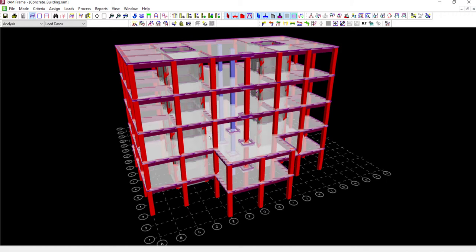Basically all the degrees of freedom are consolidated into a single degree of freedom along each direction. So for this kind of structure, we have reduced the degrees of freedom significantly from semi-rigid to rigid. And that's the reason it will consume a little amount of time compared to the scenario where you have meshed the plate and you have used the semi-rigid diaphragm. Now, please note that in RAM Structural System, although you have defined it as a rigid diaphragm, it will still include the plate element here. Just the in-plane rigidity would be infinitely high.